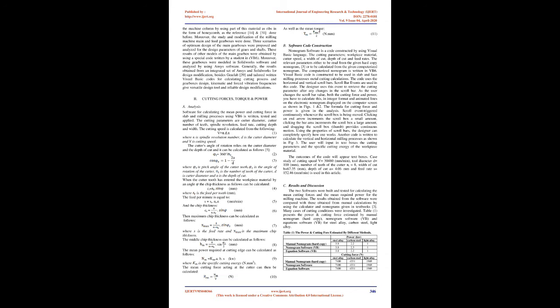A comparison of the data obtained from experimental modal analysis and the theoretical data obtained from Ansys revealed that the natural frequencies and corresponding mode shapes are in good agreement for the gearbox structure model. The well-correlated results between experimental and theoretical prove the validation of Ansys to construct a good design [32]. The validated FE model by Ansys could be used in the design process with greater confidence in the calculated mechanical properties of machine tool structures and/or parts.